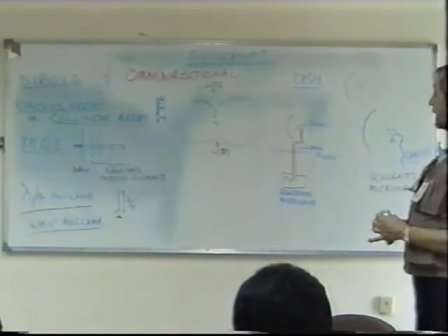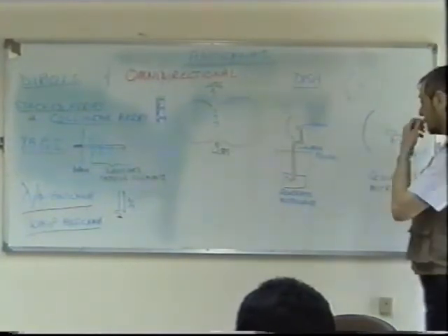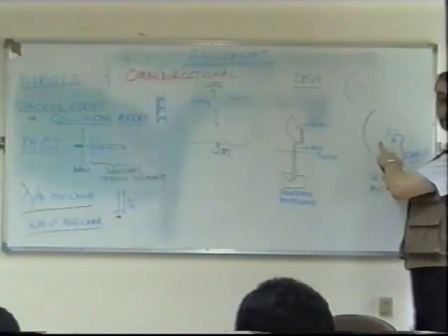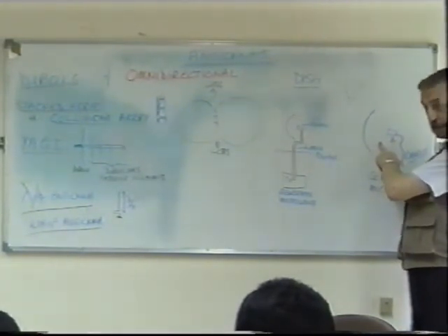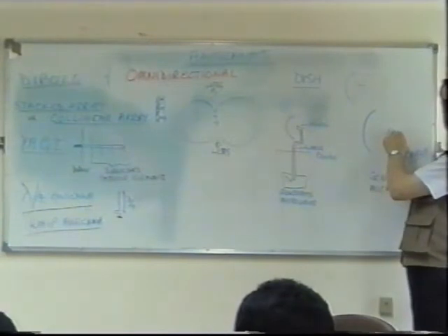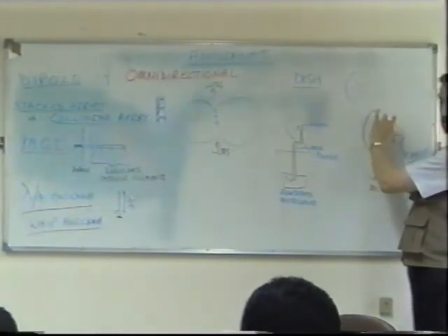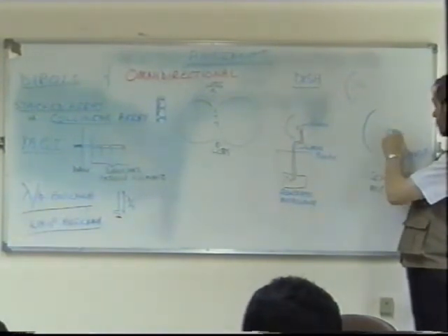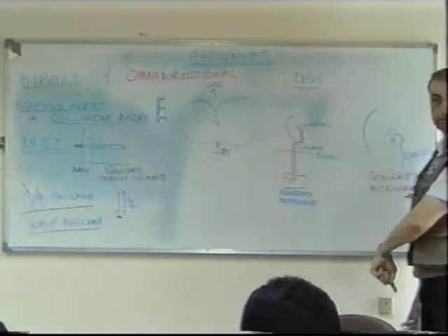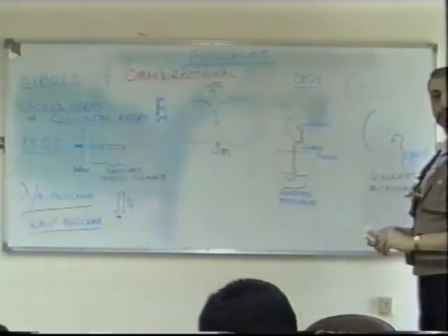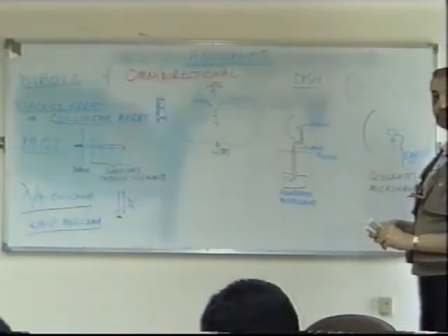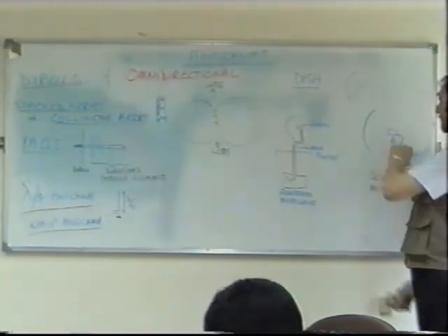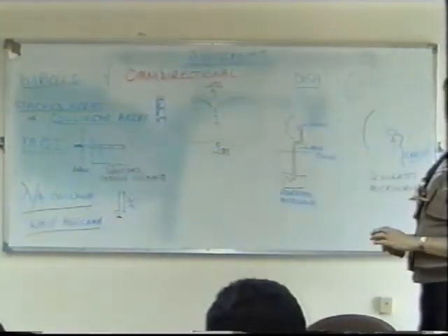Or a TV broadcast? It can be, yes. If you're using this as a TV receiver, like a dish antenna for receiving a satellite TV signal, this we call an LNB. It receives the microwaves and then changes it to another type of signal, not a microwave signal, to go down the cable to your decoder. So the device steps down the frequency. Yes, that's right. Technically, this is the first frequency change.